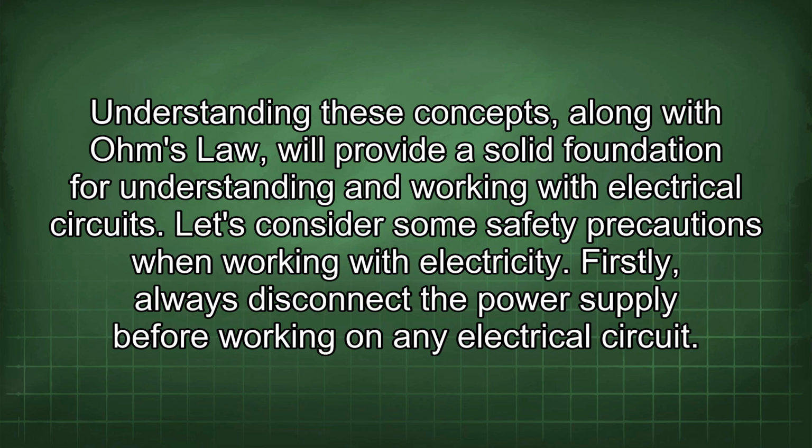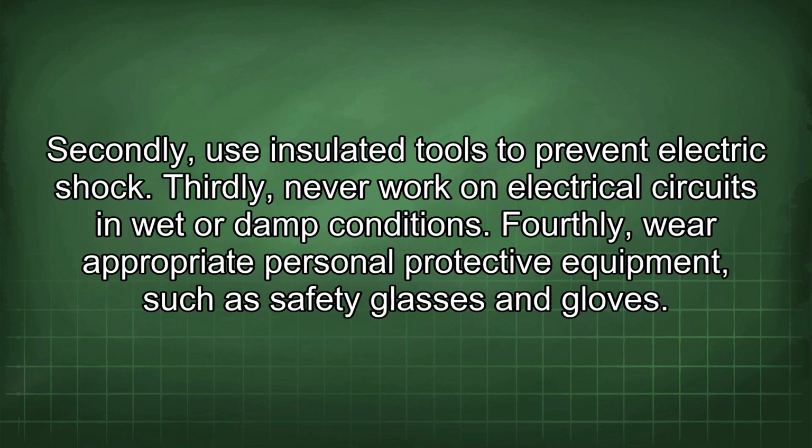Understanding these concepts, along with Ohm's law, will provide a solid foundation for understanding and working with electrical circuits. Let's consider some safety precautions when working with electricity. Firstly, always disconnect the power supply before working on any electrical circuit. Secondly, use insulated tools to prevent electric shock.